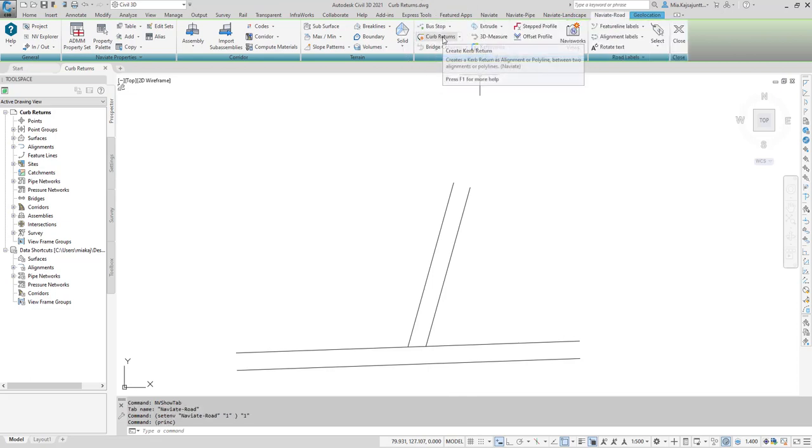Pick the points on the straights. The first point on straight 1 will be the endpoint of the first line. The second point on straight 1 is where the 2 lines meet. Pick the first point for the second straight, which again is where they meet. The second point on the second straight will be the endpoint of the second line.